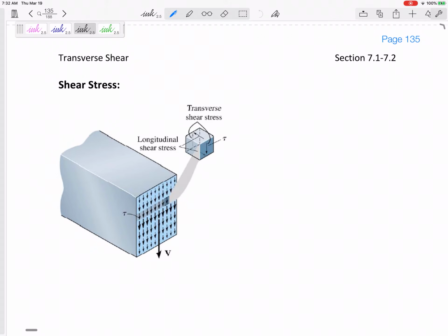All right. So last section, we're talking about how the M creates bending stress, right? The internal moment M creates a bending stress of My over I. We already knew that the internal normal force N creates N over A uniform stress, N over A.